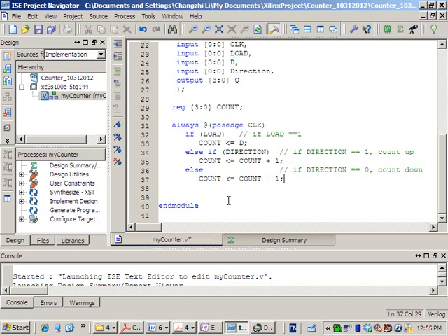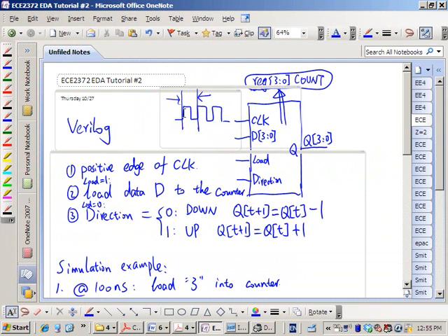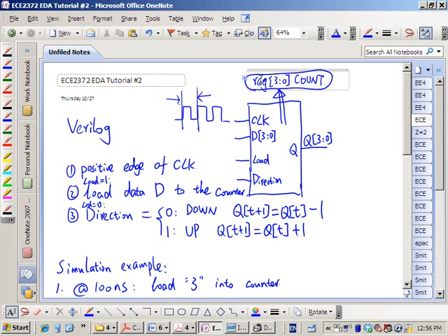And anything else? Do you have anything else in our mind? What else do we have to do? So now, at every rising edge of the clock, we have made the decision, we have either passed the input into the register, or we update the register, right? And the next thing we haven't done is we haven't passed the register value to the output.